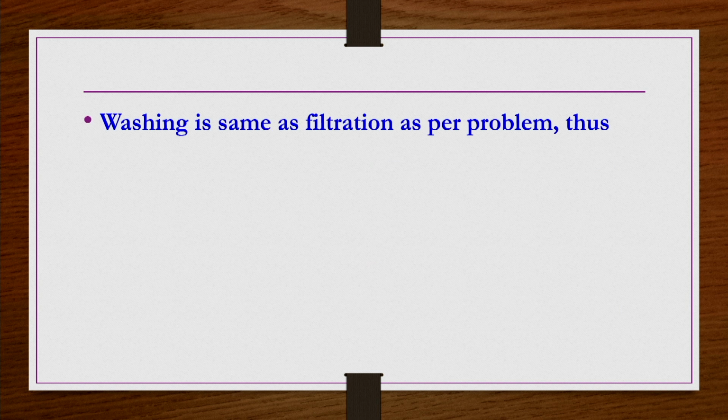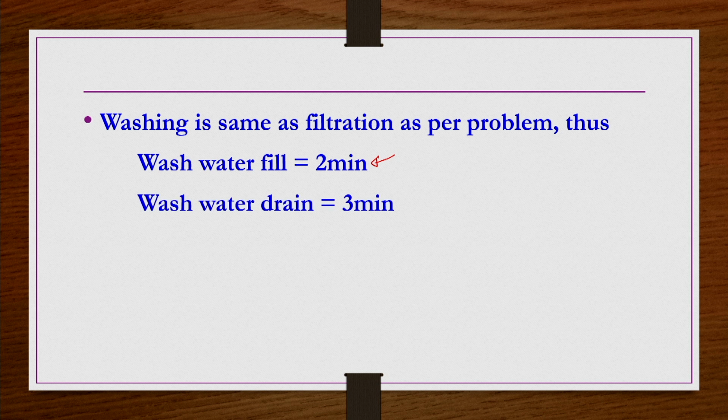But we should also include the washing time. In the washing, wash water filling is required, so that is 2 minutes given. Wash water draining time is 3 minutes, because the same way as the filtration, the washing is also taking place. So, whatever the draining or filling times are for the filtration, the same times should be taken for the washing as well.